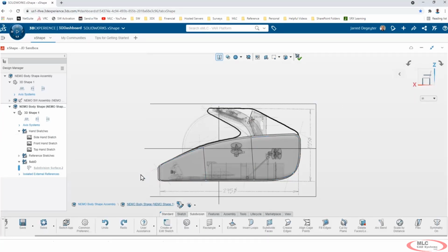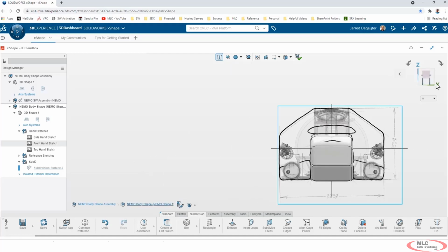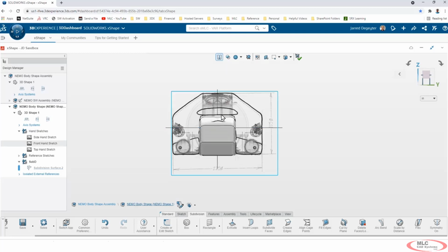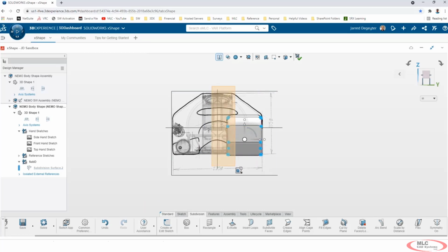So what I want to do now, I want to make this lower little front left corner match more closely with the sketch view. So I'll just do a quick box select, drag it into position. We'll rotate around to our front view, and you can see how everything's sort of centered right here. Whenever I drop that in initially, it just stayed centered. So I'm going to select all of the entities, doing a Control-A, and then just drag that into position to where it more closely matches my sketch image. And then I'll just select those left sides, drag that into shape.